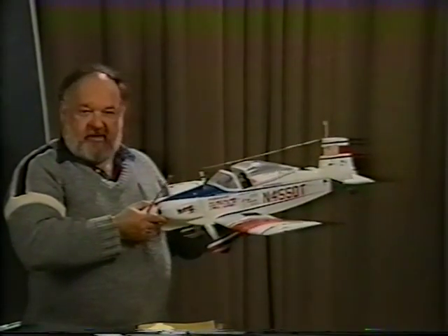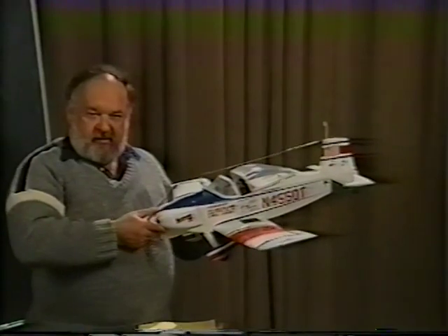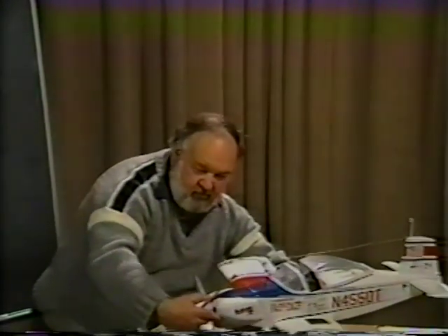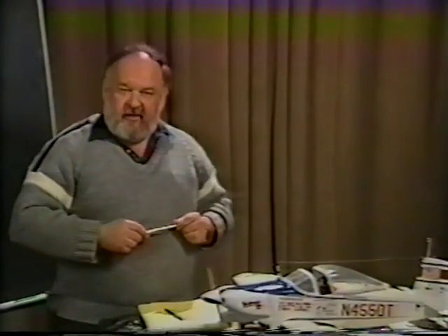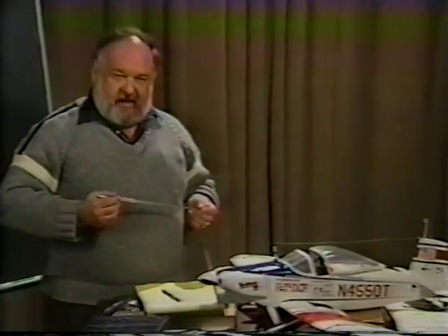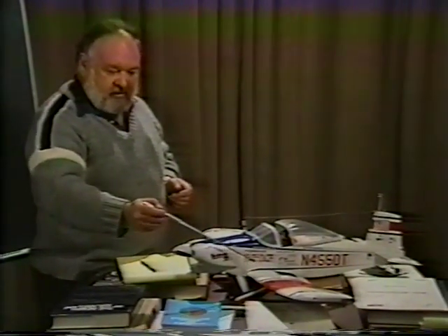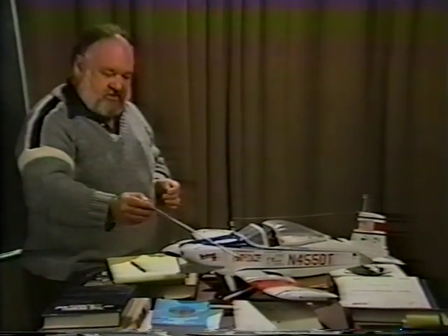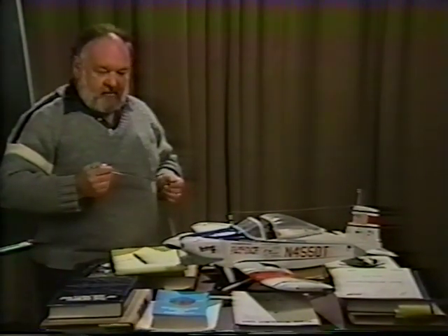That's a pretty clever approach, because a lot of times the designer will have the break on the inboard section of the wing close to the fuselage, but that also happens to be where the highest stress concentrations would be, because the loads are the highest on the spar right inboard. So in this case he probably saved some weight and made it a much simpler design by making it a one-piece spar with the breaks in the outboard portion.